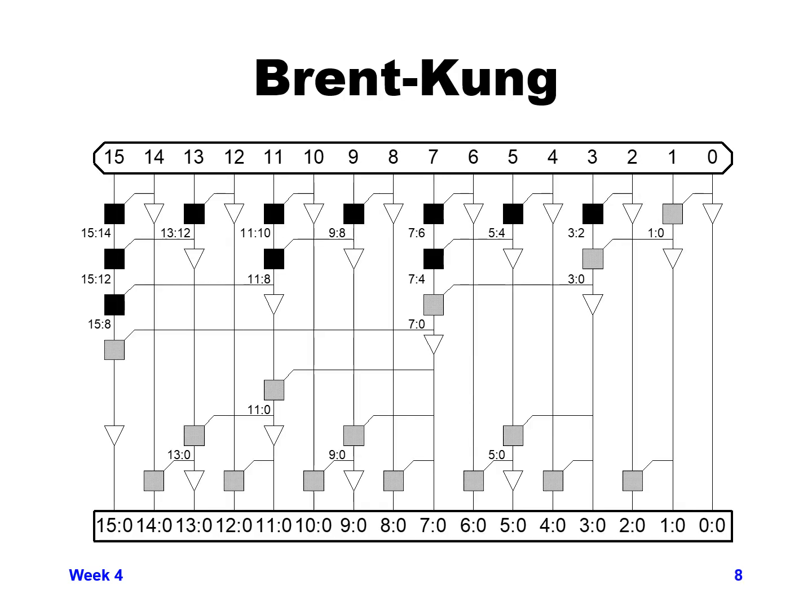So the Brent-Kung adder is an adder that goes by a log scale. It first calculates prefixes for a 2-bit group, and then it uses the resulting output from that to calculate prefixes for a 4-bit group, uses the result from that to calculate prefixes for an 8-bit group, and so forth. So you can see one example here for a 16-bit adder.